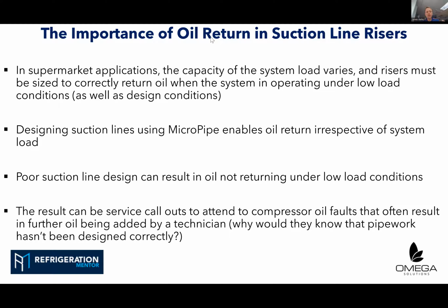So for example, risers, vertical pipework, under low load conditions, it's really important that it's sized appropriately, so we're going to get that oil return under all conditions, as well as in the middle of summer on full design conditions.